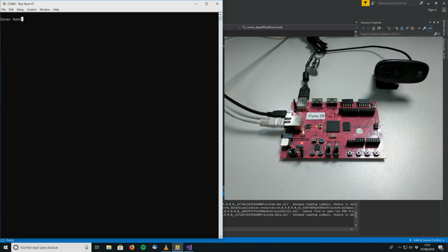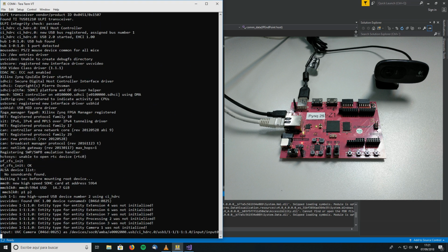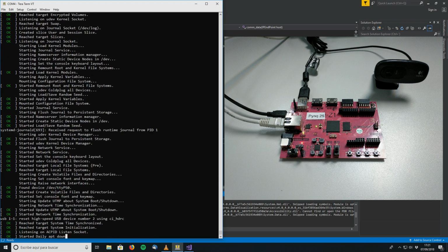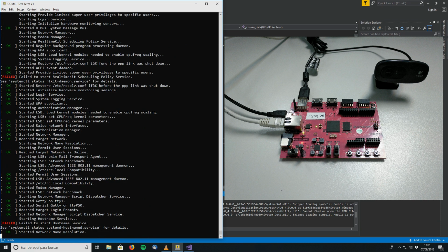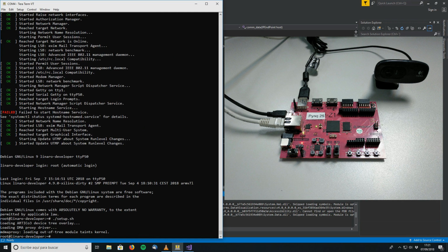The proof of concept demonstrator of the MDC-ARTICO integration runs on a ping board, which features an FPGA plus an ARM-based dual-core microprocessor. The setup requires a USB camera and a desktop or laptop computer to run the user application. The first step is to put the embedded Linux on the board and run the target application.